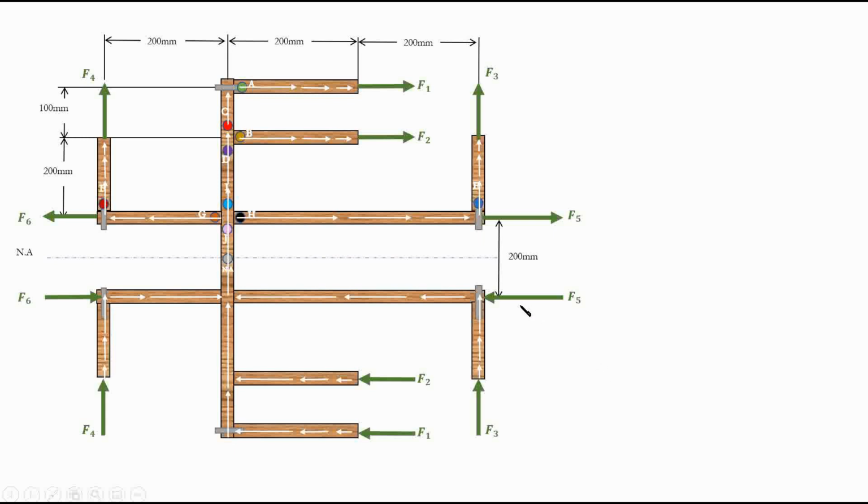Now that we know all of these forces, we can basically find the shear center, right? What is the idea behind shear center? We're finding the shear center to avoid additional twist, right? So if I take the moment of all of these forces about any point, my segment should be in equilibrium, right? That's basically the idea behind the statics behind all of these questions. However, if I apply this force anywhere I like, I'm not going to end up with the result that I want. So my segment will not be in equilibrium.